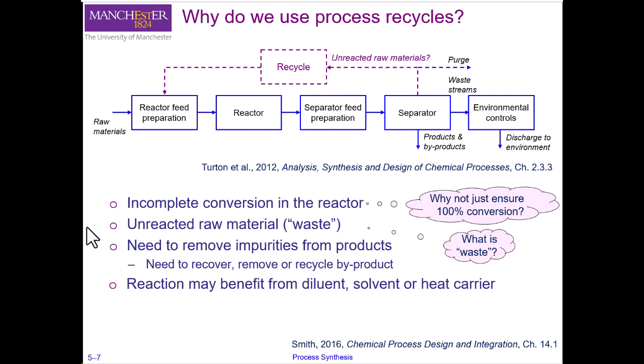Okay, and if you are recycling, this impurity is going to build up in your system, and as such it is going to increase the volume of your equipment. It's going to increase your duty because you have higher flow due to this recycling impurity. So at some stage you have to take this impurity out of your system, and sometimes we use